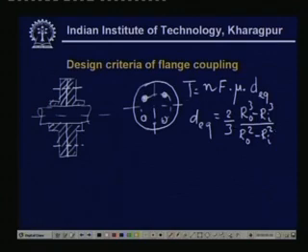Now, this torque transmission will be the same as the transmission on the shaft, and if you use this formula, then you get F. Now, F is related to AB, the bolt cross section. This will be the minimum cross section, that is at the root of the thread, times sigma tension allowable.